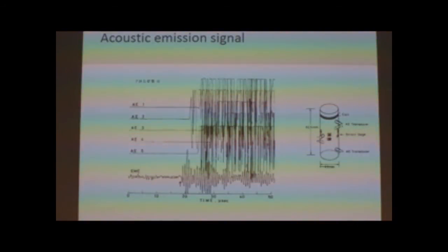Well, the sound speed of acoustic waves is slow. Electromagnetic waves go really fast. So when the fracture happens, the electromagnetic emission occurs, and at light speed you get to the detector. And you can use that for timing to figure out how long it takes for the other sensors, and you can use that as a way of doing your sonar.